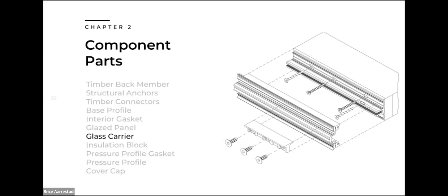The last piece on the glazing aspect here is the glass carrier. These are ABS clips that are attached to the transom, and these are really just there to hold up the glaze panel, typically an IGU. So it's not resting on the base profile, which would, in most cases, void the warranty of that glass. There are a lot of different varieties that we can do depending on the thickness of your glaze panel, and the number of glass carriers required per panel is another thing that we calculate to make sure that all the gravity loads are carried.